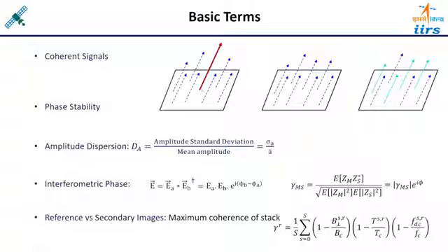One scatterer is responding with backscatter energy very strongly. The backscatter information corresponding to this red response is very high, and the backscatter from the other targets represented by the blue colors is not that high, or you can say a moderate level of backscattering is happening from the other types of targets. Okay, so within this resolution cell two types of scatterers are there. One category of scatterers is responding moderately, and another category is responding very strongly.